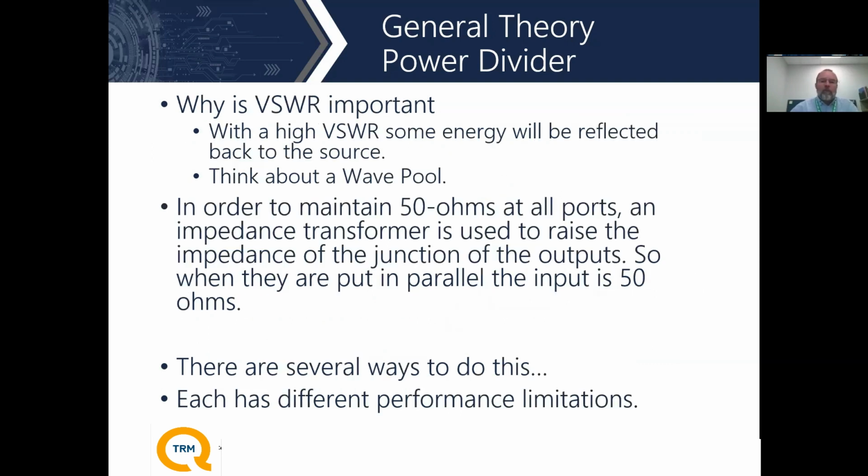Why is VSWR important? Because if you have a high VSWR, it means that you're taking energy and reflecting it back to the source. That is really what VSWR means, voltage standing wave ratio. It is the ratio of energy that leaves the source versus how much energy is being reflected back to the